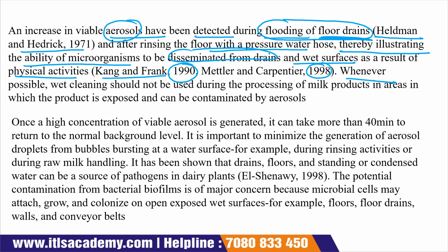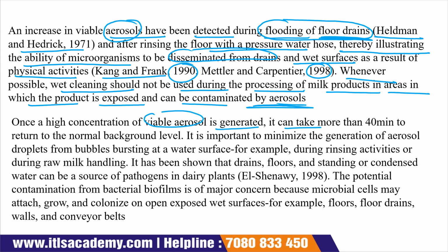Whenever possible, wet cleaning should not be used during the processing of milk product in areas in which the product is exposed and can be contaminated by the aerosols. Once there is a high concentration of this viable aerosol, it can take more than 40 minutes to return to the normal background level.